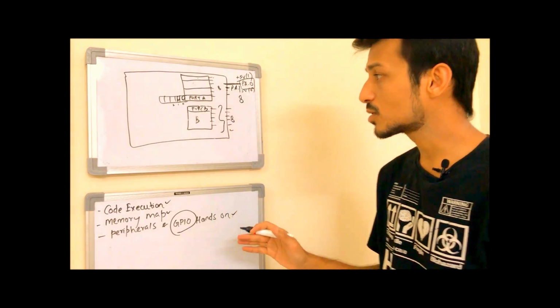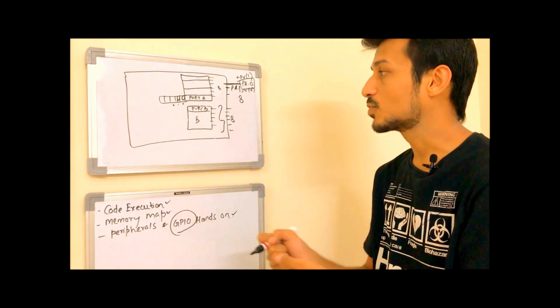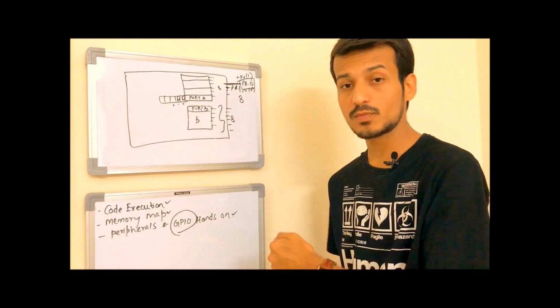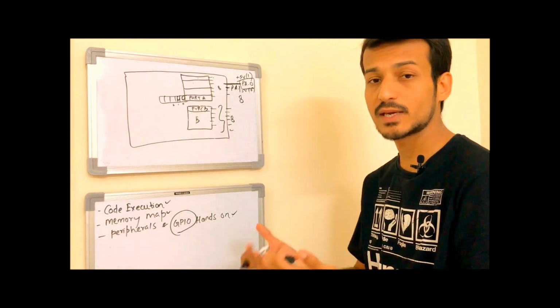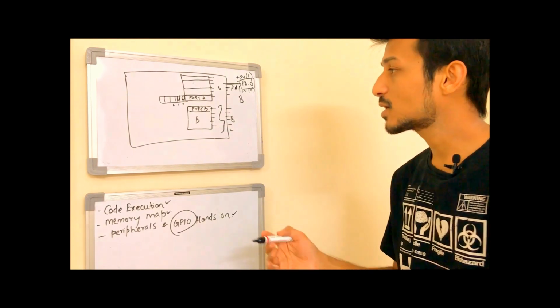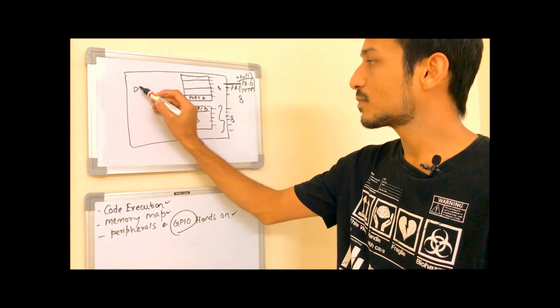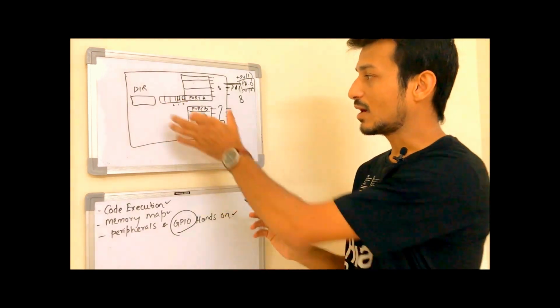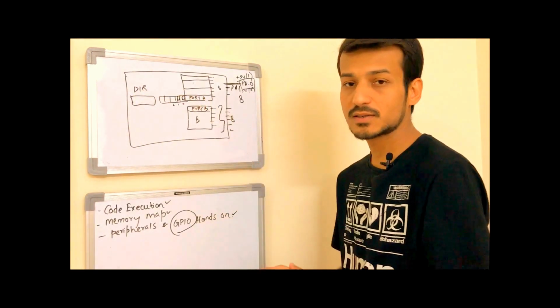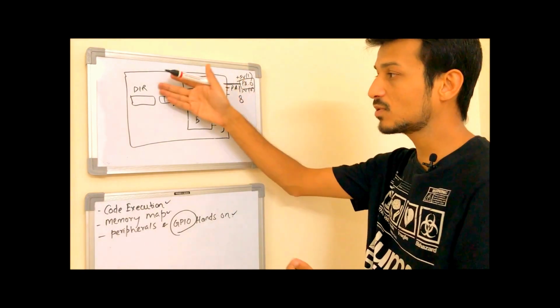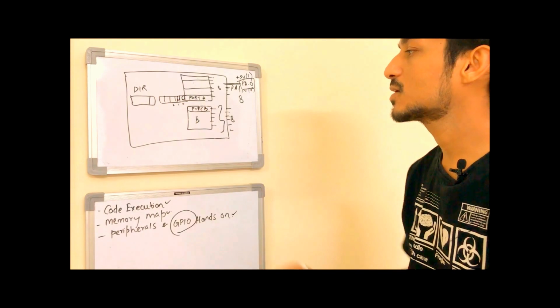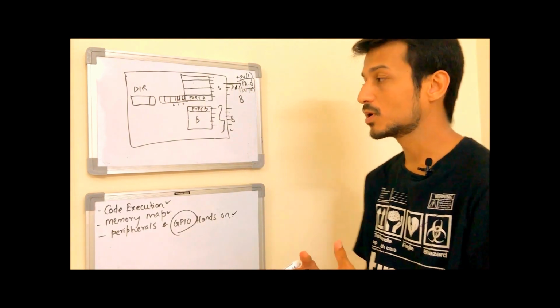But GPIO is not only about providing output. GPIO means general purpose input output. So there should be some means of taking an input also. That's how the direction register is used. With every port there will be a direction register, or with every pin there will be a direction register associated, which will tell whether this bit is going to be an input or output.